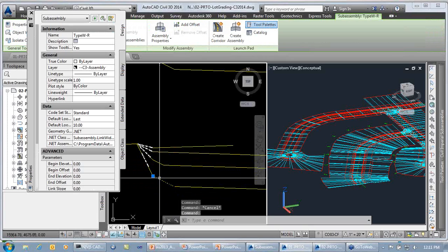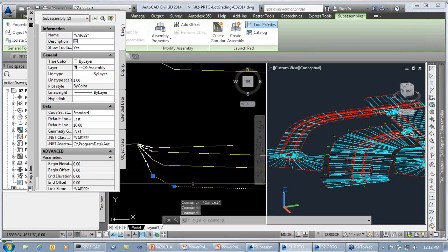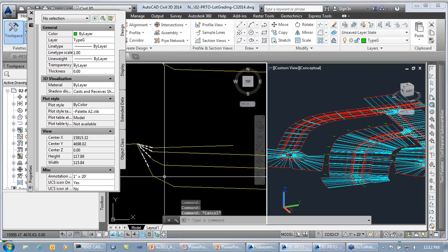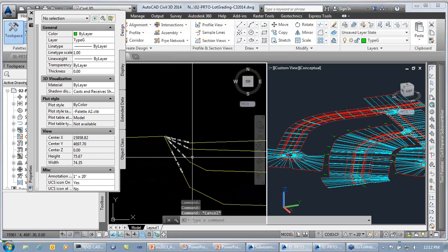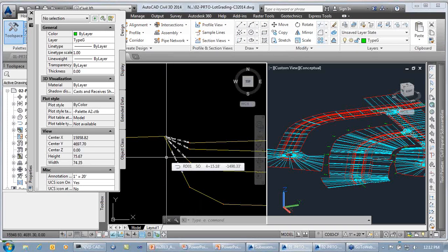And if you find the type W, go down 8 feet and then continue to the rear of the lot at 3% as well. Okay. I've kind of gotten lazy. The way I've done it here, all 4 of these potentially could evaluate to true, which means I'm going to get lots on top of lots. So I really need to be careful that I don't overlap my target polylines in my drawing, to make sure I don't get lots drawn on top of lots.